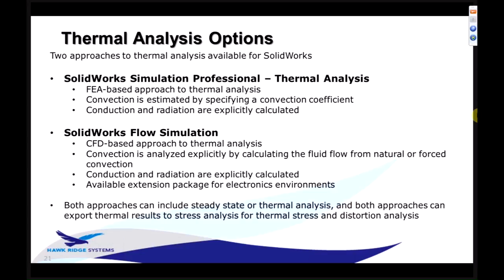SOLIDWORKS Flow Simulation, again, is a CFD-based approach to thermal analysis. It's going to include all the fluid flow stuff we just looked at, as well as the heat transfer processes. And when we do convection in that tool, we calculate the convective rate precisely from how the fluid moves and what sort of fluid it is. What that means as a net result is that the CFD approach is a lot more accurate because it makes fewer assumptions than an FEA approach. The FEA approach runs a little faster, it's in a lower cost software package, but doesn't have the accuracy.